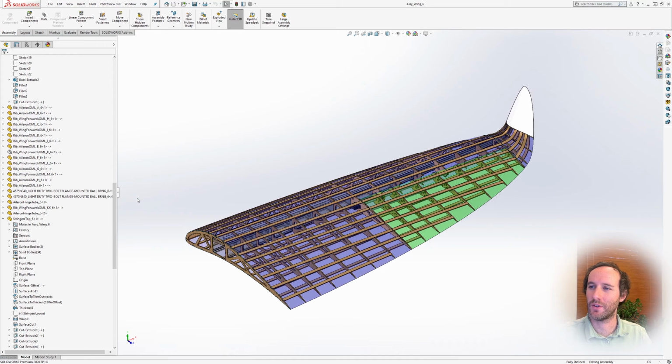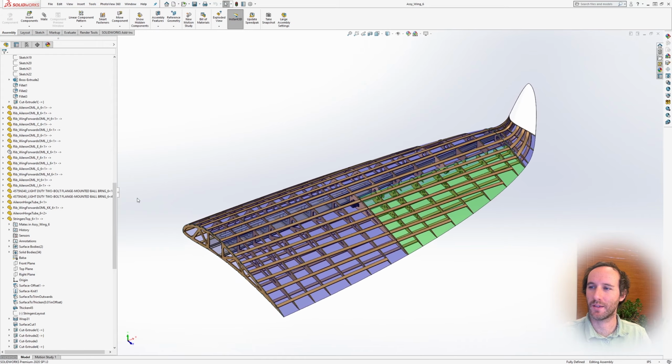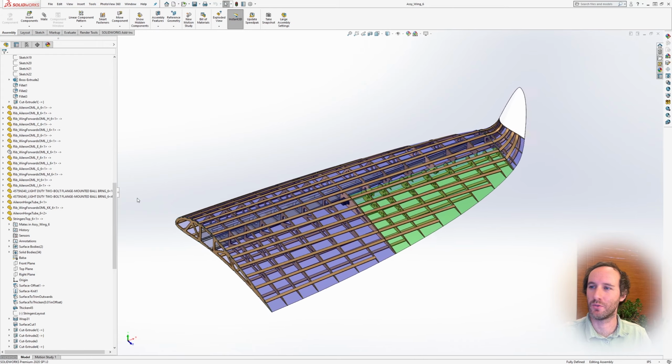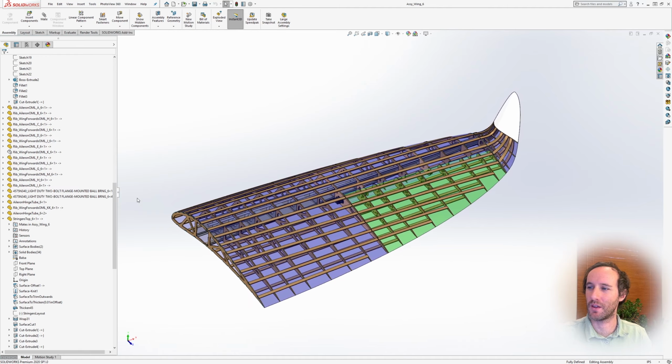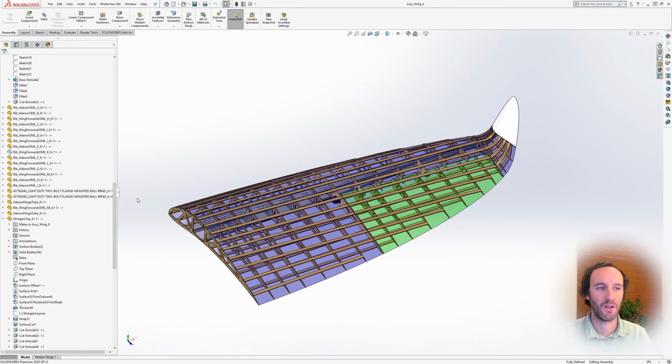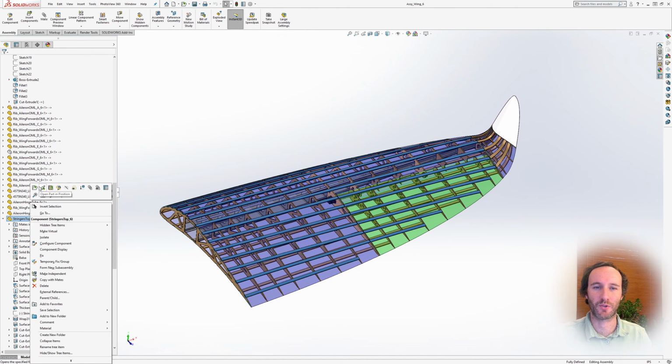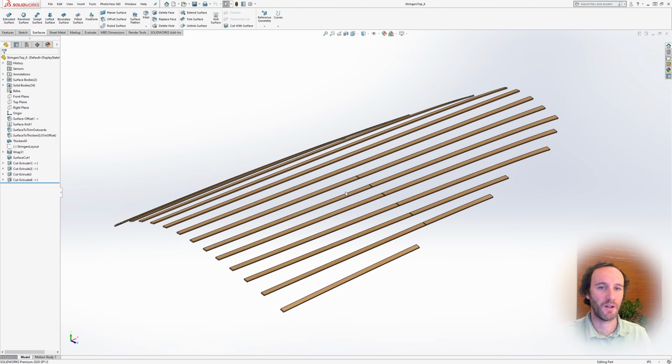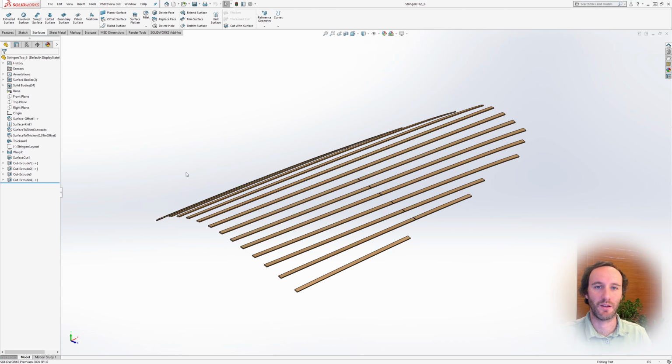Now another caveat is the wrap, as a numerical solution, seems to recalculate differently than other features. If you rebuild with Control Q inside a part with a wrap, it seems to recalculate it even if the inputs to the wrap are unchanged. So it could refresh downstream based on a potentially slightly different wrap solution.